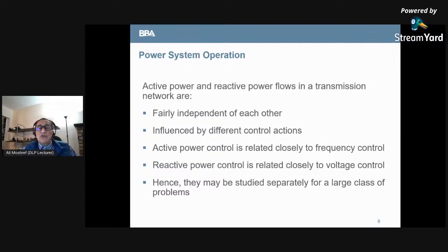And active power is closely related to frequency control because that is actually a law of nature. You know, force equals mass times acceleration, right? The second law of Newton, the rotation law. It is exactly that, which means if we have a balance of active power, if we can satisfy the load and generation balance, then frequency stays constant. In March 2015, Turkey's network went through a blackout. If some of you remember, the system frequency went down to, I think, 47 hertz.